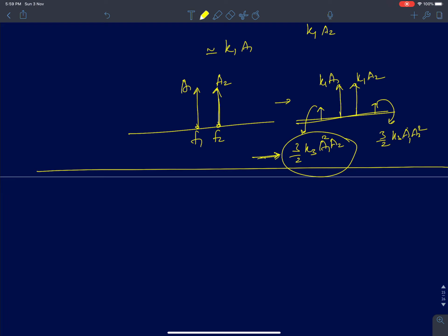Two interferers can generate components at frequencies very close to them, so if your desired channel is very close to two interfering signals, they can generate some noise or unwanted components in our desired channel.